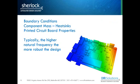You do have to consider component mass, heat sinks, and the printed circuit board properties and how they affect the natural frequency. The rule of thumb is typically the higher the natural frequency of the board, the more robust the design.